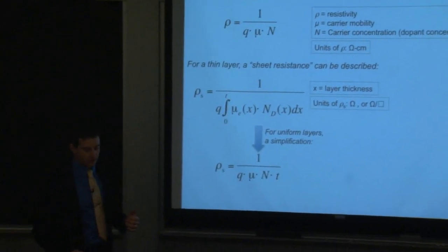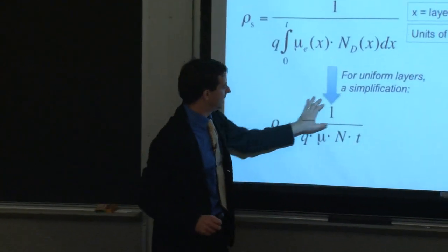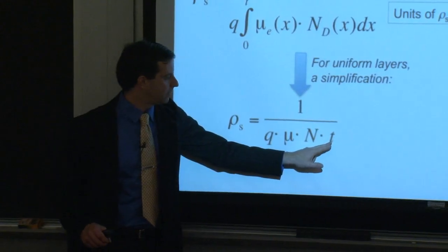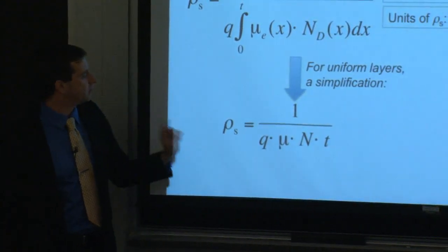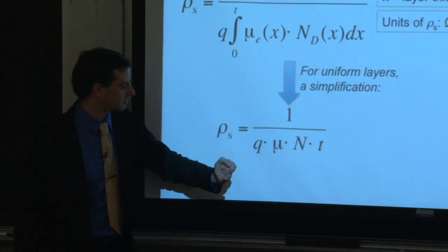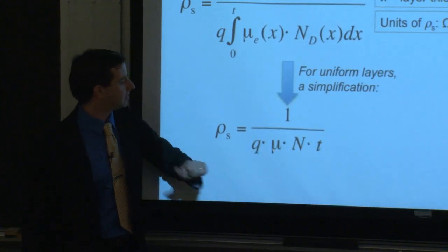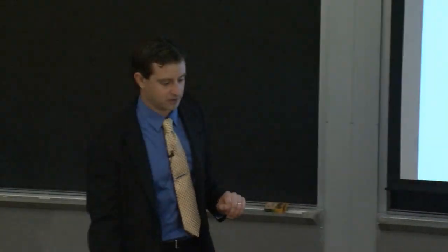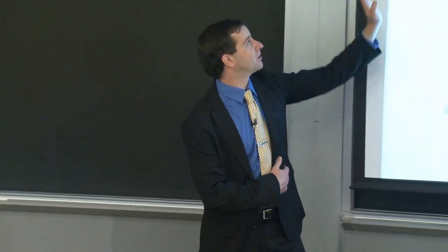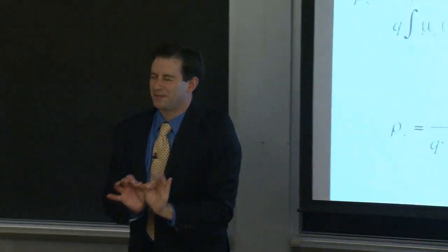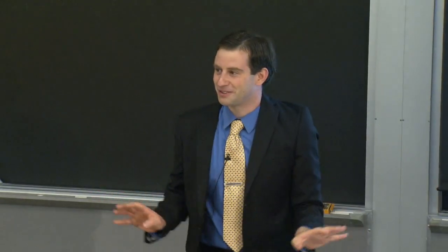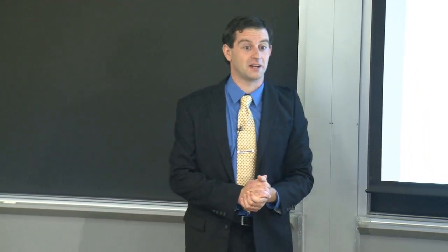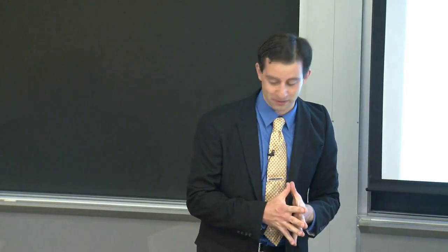Right? So folks with me so far, for the emitter sheet resistance to be low, we need the thickness to be thick enough, the carrier density to be high enough, and the mobility to be large enough. And oftentimes, the resistivity of a material, you might spend months trying to optimize the resistivity of your emitter region. For those doing thin film materials, you might be working on zinc oxide, aluminum doped or fluorine doped zinc oxide, for instance.